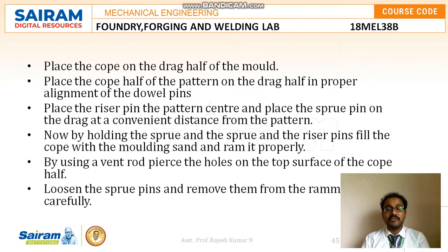Place the cope on the drag half of the mold. Place the cope half of the pattern on the drag half in proper alignment of the dowel pins. Place the riser pin in the pattern center and place the screw pin on the drag at a convenient distance from the pattern. Now by holding the screw and riser pins, fill the cope with the molding sand and ram it properly. By using a vent rod, pierce holes in the top surface of the cope half.